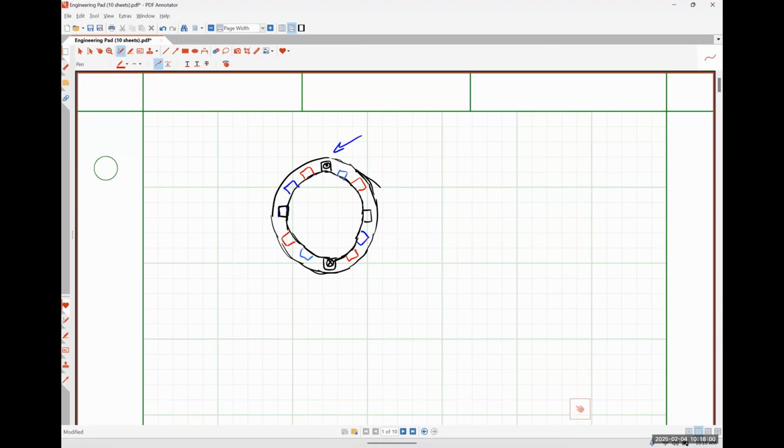Essentially, our rotor only has to travel half the distance it had before it sees the opposite polarity, and so it's going to spin slowly because of that. The more poles we have, the less distance it has to travel before it sees that same phase of signal. That's why it spins more slowly. So poles are related to the speed at which it's spinning.